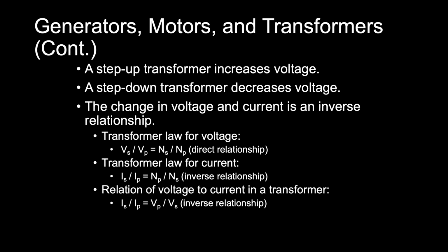And then the voltage of the secondary equals 5 times 110. And then multiply that, and so your secondary coil voltage would be 550.